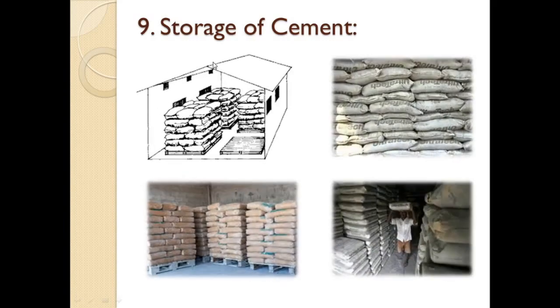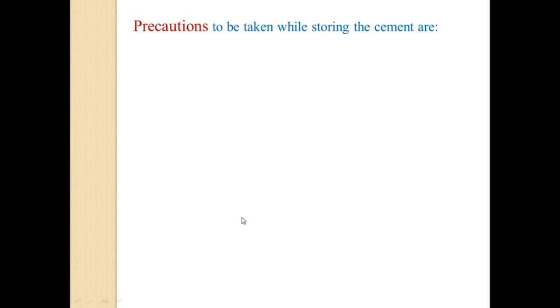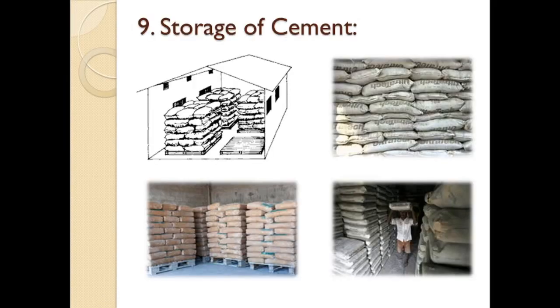How can we store the cement? Here we can see some cement bags being stored. What are the precautions to be taken while storing cement? Cement is stored carefully because it is hygroscopic in nature and therefore can easily absorb moisture from the air. So cement should be protected from dampness, and